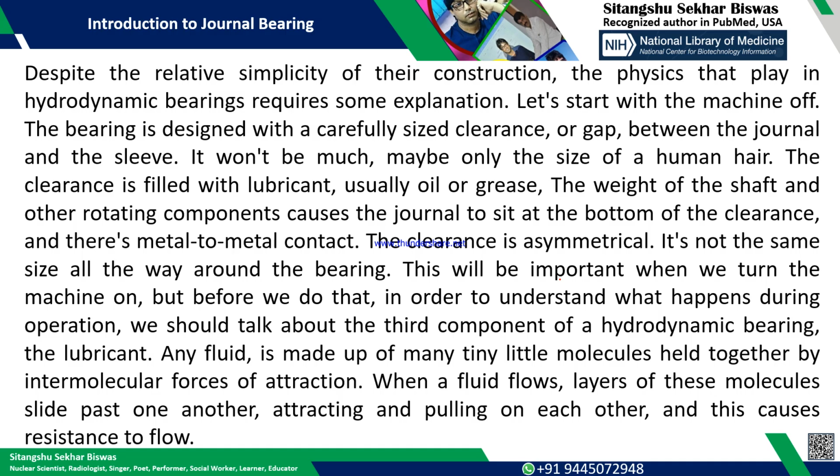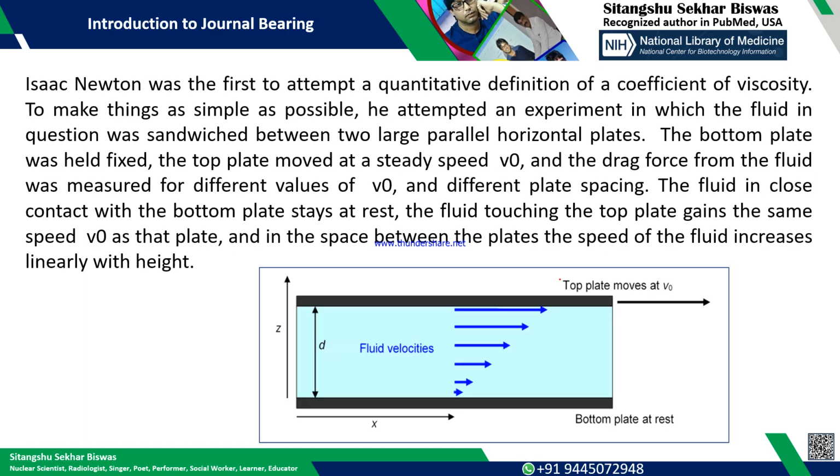So when a liquid flows, the layers of these molecules slide past one another. One layer attracts the subsequent one, and they pull on each other. This causes resistance to flow, which is indirectly measured with a parameter called viscosity.